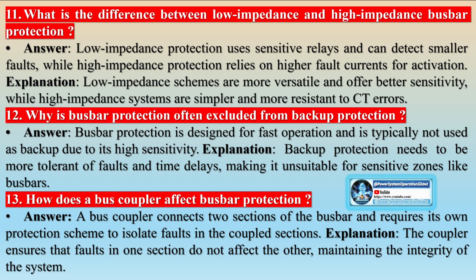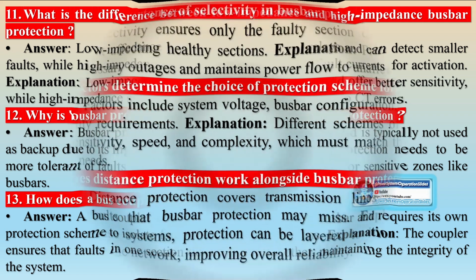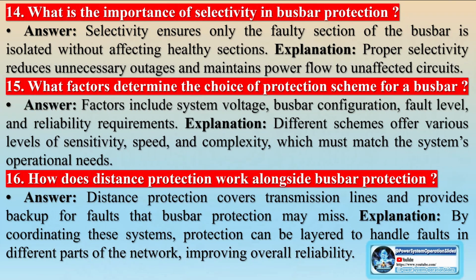Direct and selective tripping. Direct tripping. This involves the immediate tripping of the remote end of a feeder connected to a double busbar substation when busbar protection operates. It is achieved through direct transfer trip (DTT) and/or unstabilization of circuit protection by busbar protection trip relays or back trip receive trip relays with selectable links inserted. Interlocked current trip relay links should also be inserted. Note that unstabilization may not be used in modern systems but exists in some legacy installations.